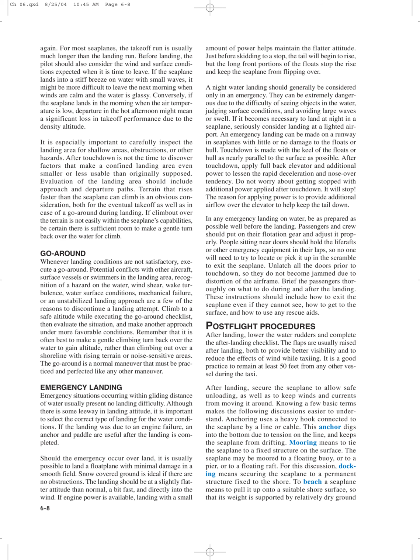Remember that it is often best to make a gentle climbing turn back over the water to gain altitude, rather than climbing out over a shoreline with rising terrain or noise-sensitive areas. The go-around is a normal maneuver that must be practiced and perfected like any other maneuver.